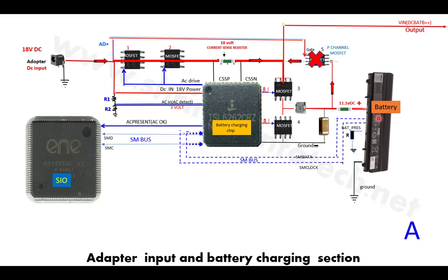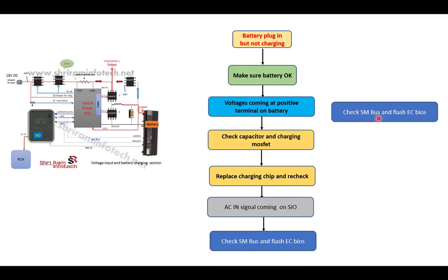Now suppose your battery is not charging, then what to do? We'll go to the flowchart and see. If your battery is not charging, first make sure your battery is okay. Try to put in another battery and check, to verify and confirm that your battery is okay.